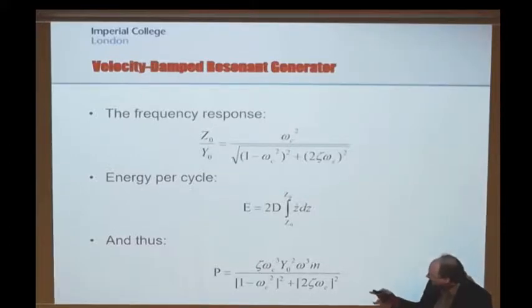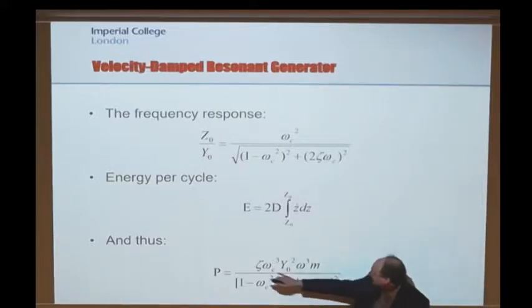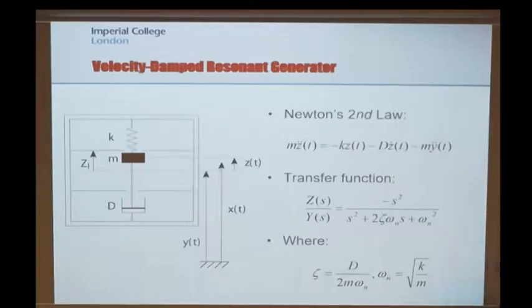So we're basically saying I've got a linear damper, I've got a mass on a spring doing work against that damping mechanism, and that is the power that I will generate in my energy harvesting device. So it's dependent here on the damping factor that I achieve, and as we've seen, I can change the damping factor by changing the damping constant, and we've already seen I can change the damping constant in this case by changing the resistive load on the device.